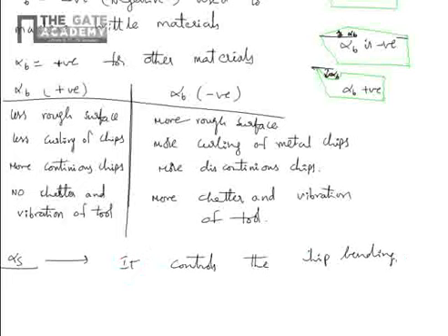So how does it control? As the side rake angle increases, the amount the chip has to bend decreases. Hence the power required to part and bend the chip decreases as the side rake angle increases. Heat generation will be high if you increase it, as a fairly large part of the power required to part and bend the chip is transformed into heat. The thickness of the chip is largely determined by the amount of feed per revolution.